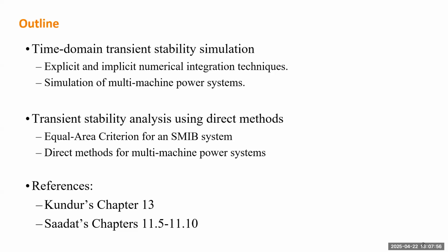All right, so in this session, we're going to cover two approaches to study the transient stability. The first one is the time domain transient stability simulation. So in this part, we're going to introduce the two types of integration methods to solve the dynamic model of a power system, including explicit or implicit methods. Then we'll talk about how to simulate a general power system with multiple generators.